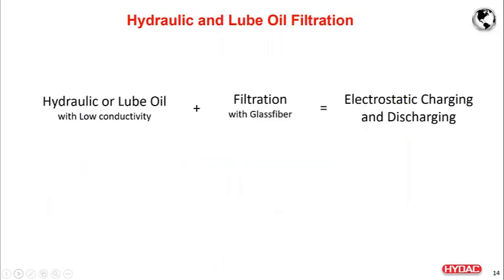So putting all of that into one equation: when you have hydraulic or lube oil with very low conductivity, and you're filtering that oil through glass fiber media, you are going to have electrostatic charging and discharging, given the very low dielectric constant. This is always going to hold true as long as you have these 2 conditions.